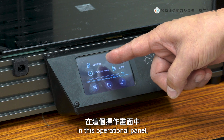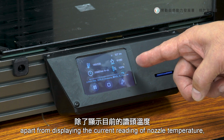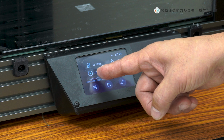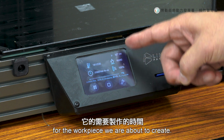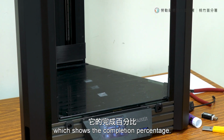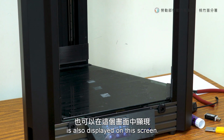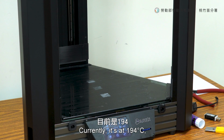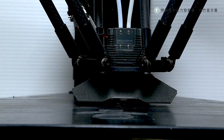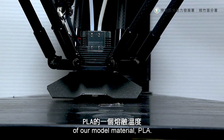By the way, in this operational panel, apart from displaying the current reading of nozzle temperature, we can also see the required manufacturing time for the workpiece we are about to create. There is a clock symbol here which shows the completion percentage. Okay, the temperature is also displaying on the screen. Currently, it's 194 degrees. We need to heat it up to 220. This 220 degrees Celsius is the melting temperature for our model material, PLA.